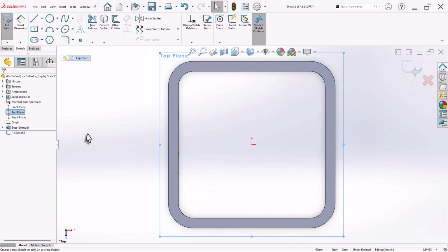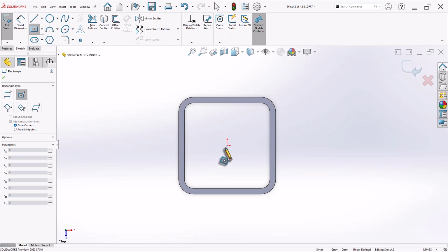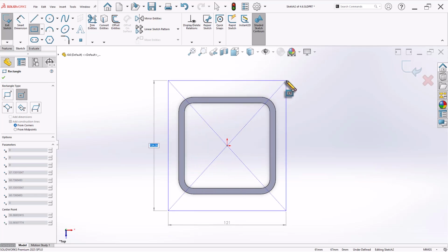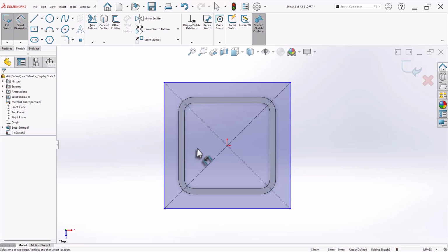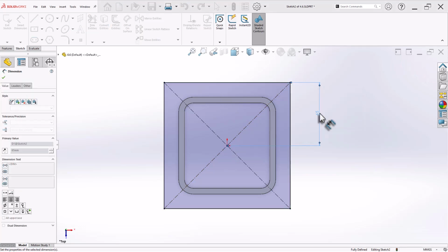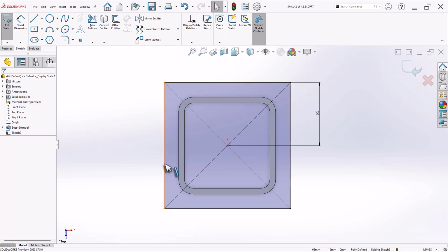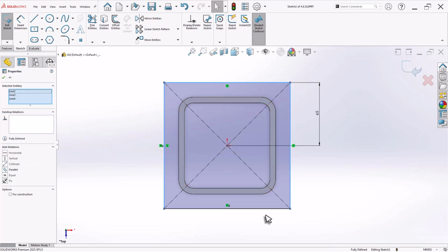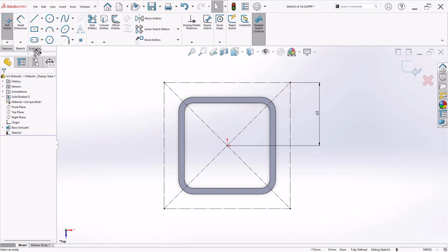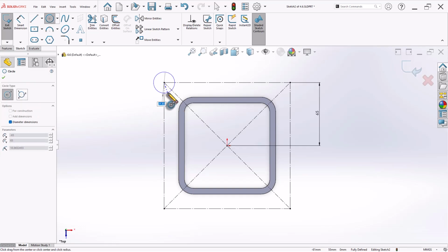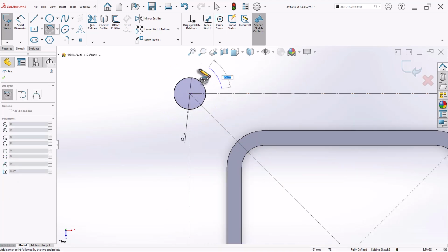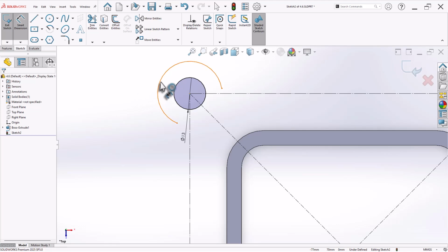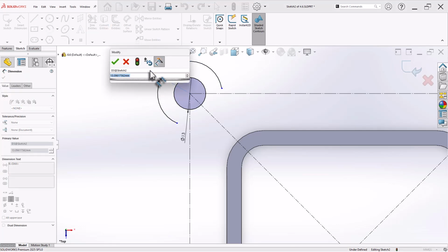Now on a top plane again, let's start sketching the center rectangle whose dimension is 130 indirectly. Let's remove it. Now let's add the typical dimensions. So from here to here it is given as 65. So it will work as a construction geometries. Now let's place circle at 4 corner. This circle is having value 13. Center point circle. So from here to here. Now radius is 25.